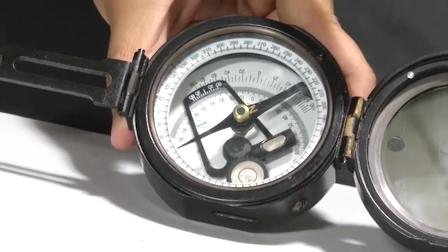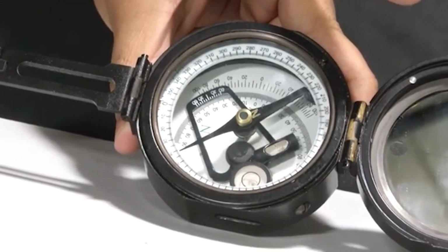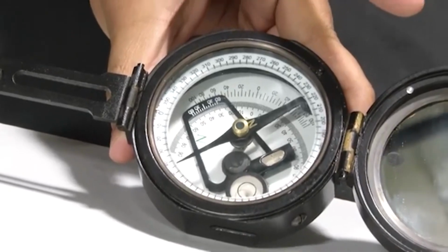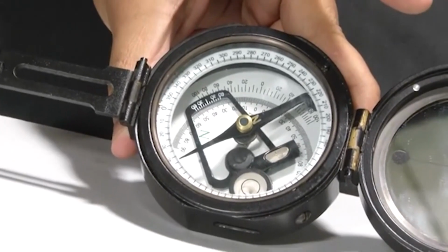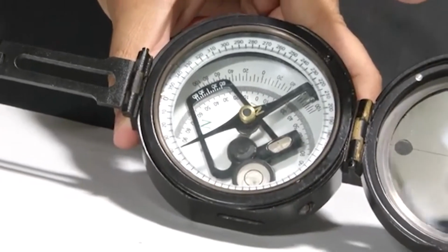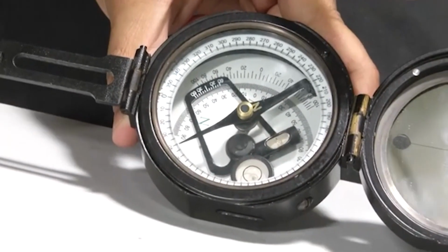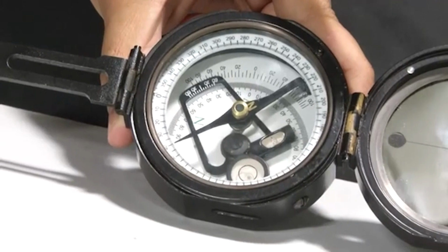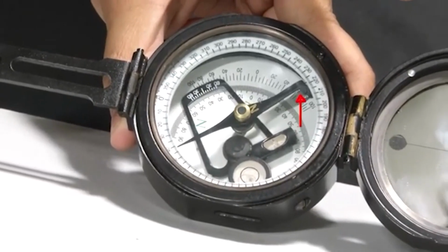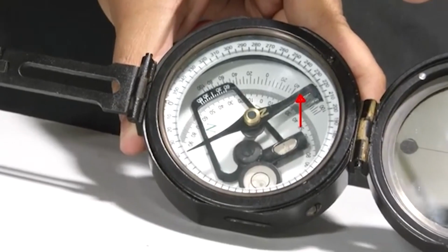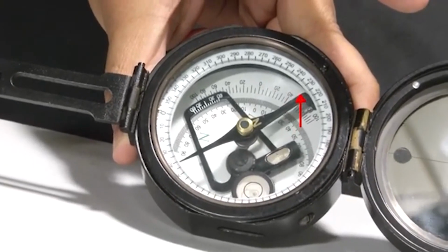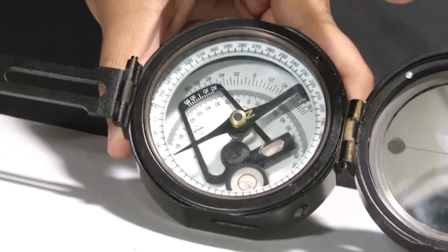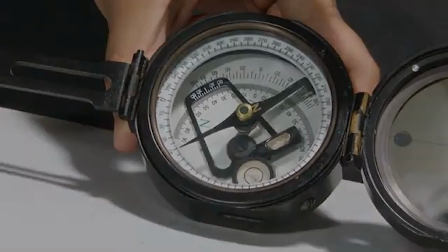In order to note the reading, it has to be carefully kept in mind that we would take the reading of the northern end of the magnetic needle to which it is pointing in the 360-degree graduated scale when the pointed arm is pointing towards the direction towards which our thumb was pointing. So when everything is ready, bubble is in center, the northern end of the magnetic needle reaches 220 degree when the pointed arm is pointing towards the direction which the thumb was pointing. So the strike in this present case is 220 degree.